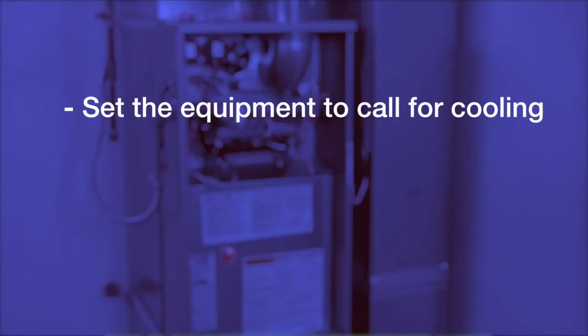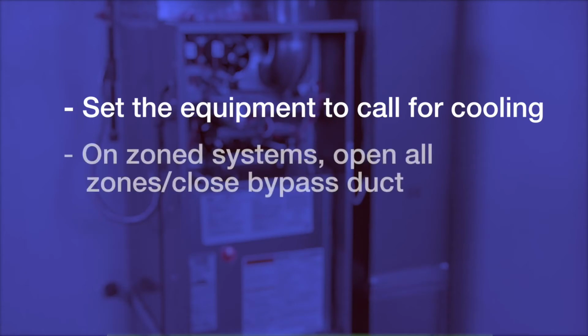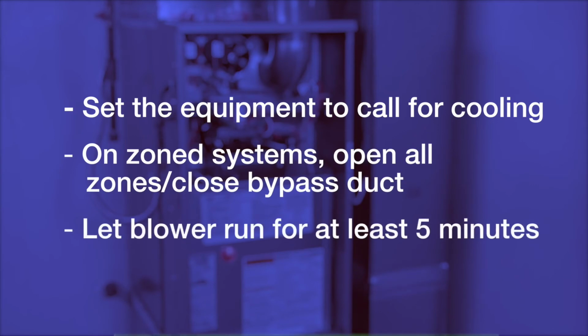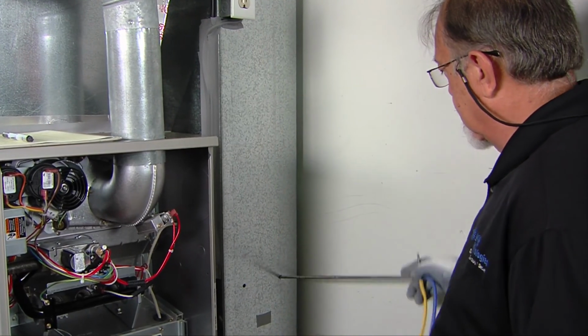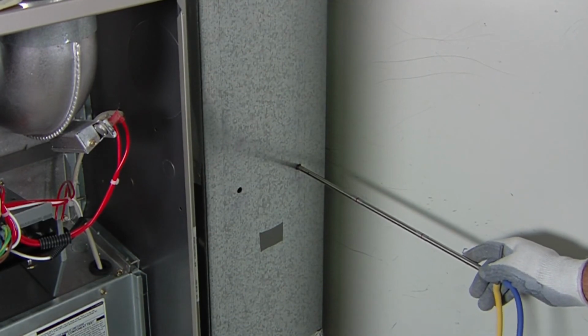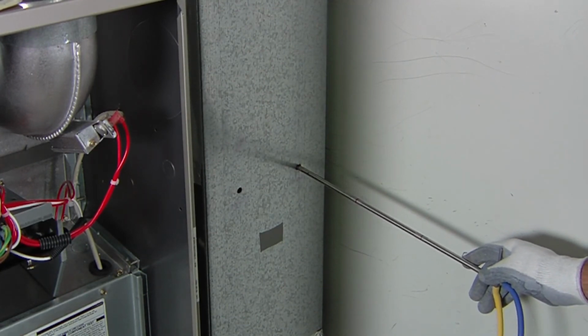Set the equipment to call for cooling at the thermostat. On zone systems, open all zones and close the bypass duct. Let the blower run for at least 5 minutes to allow the airflow in the system to stabilize. Insert the pitot tube into the hole in the duct. Make sure the pitot tube is level and the port is pointing up as you take each reading.